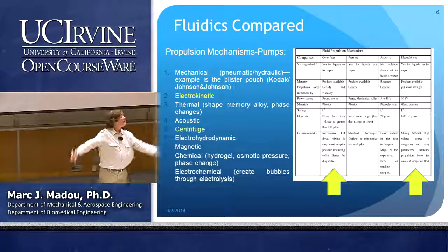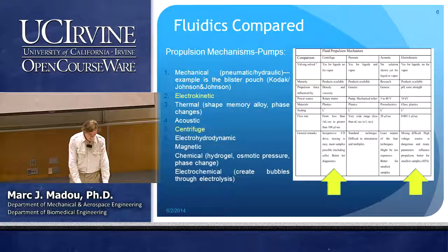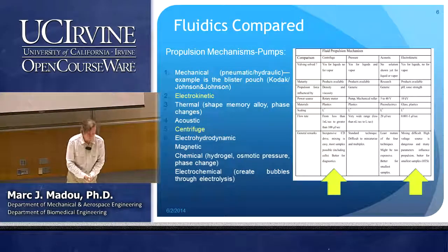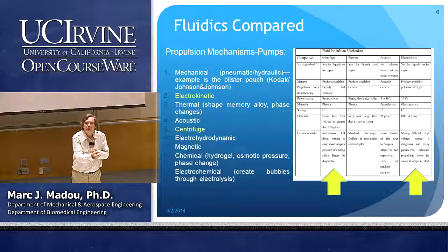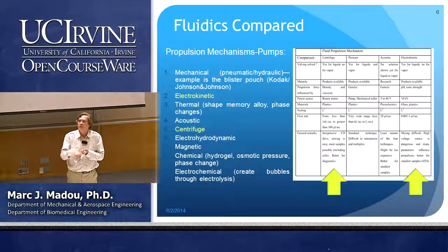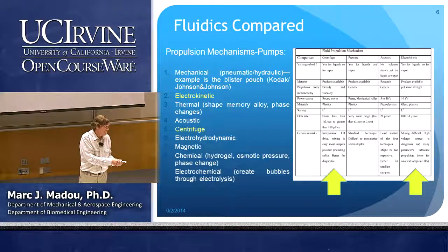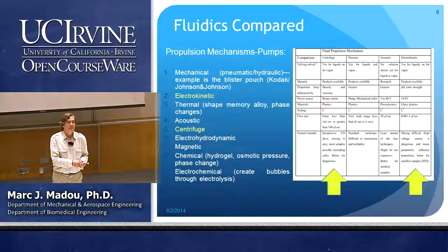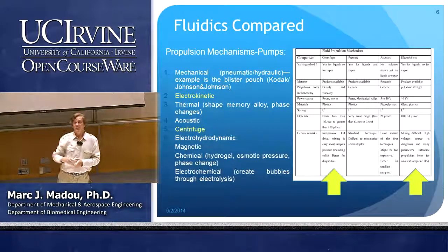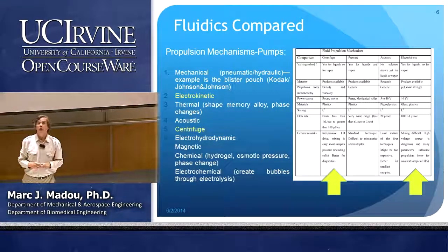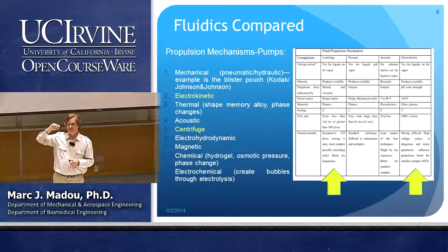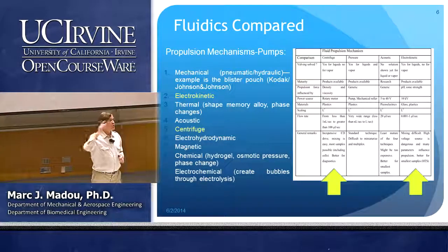Look, if I'm going to start with pressure pumping, you probably all have the same intuition. If I have a pump here, and the capillary or plastic tubing that I use becomes thinner and thinner, what will happen with the pressure? The diameter gets smaller and smaller, and the pressure shoots up dramatically, right? Check again Poiseuille's law, which gives the relation between the radius and the pressure. It goes as 1 over r to the 4th. So as r becomes smaller, the pressure shoots up dramatically.